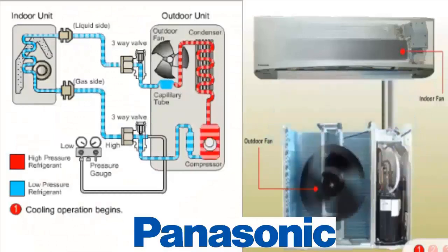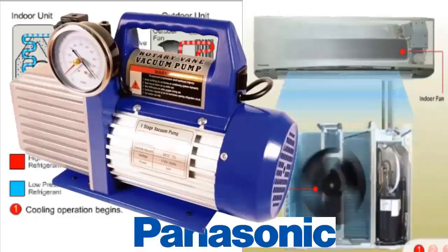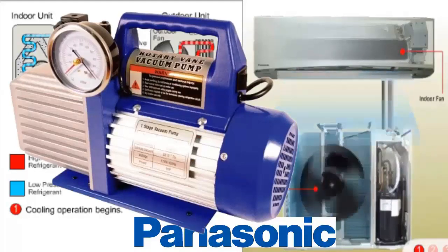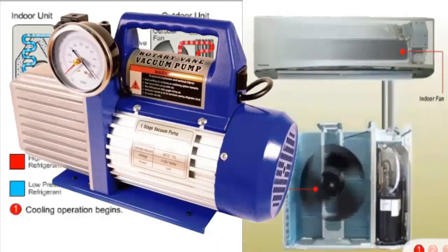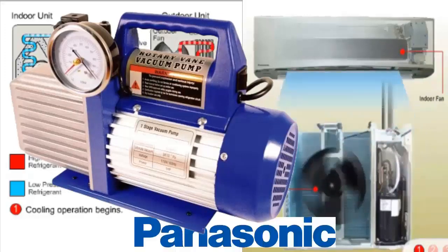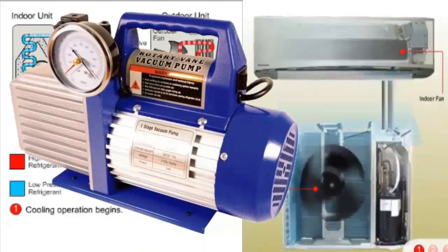Error 6. Incomplete vacuum of the system. Humidity can affect performance. Solution. A. The installer must perform a vacuum with a vacuum pump to remove moisture and air from the system before releasing the refrigerant from the outdoor unit.